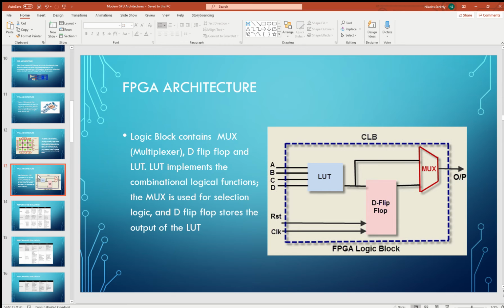The basic building block of the FPGA is the lookup table-based function generator. The number of inputs to the LUT varies from 3, 4, 6, and even 8 after experiments. Now we have adaptive LUTs that provide two outputs per single LUT with the implementation of two function generators. Xilinx Virtex 5 is the most popular FPGA. It contains a lookup table, LUT, which is connected with MUX and flip-flop as mentioned earlier. Present FPGAs consist of about hundreds of thousands of configurable logic blocks. For configuring the FPGA, ModelSim and Xilinx ISE software are used to generate a bitstream file and for development.